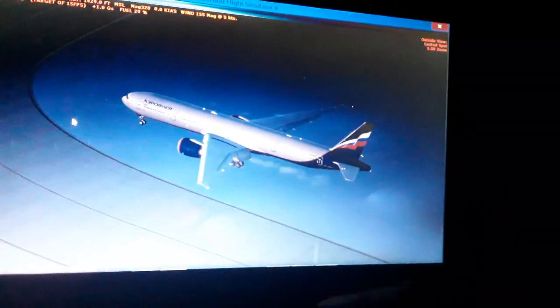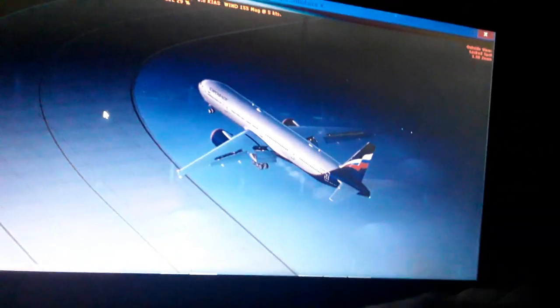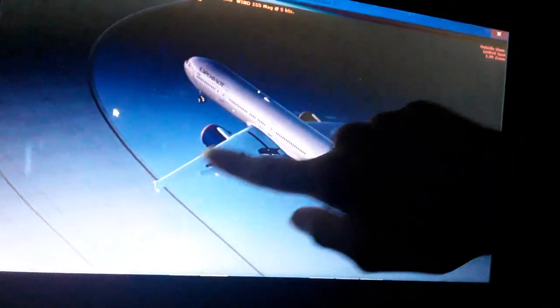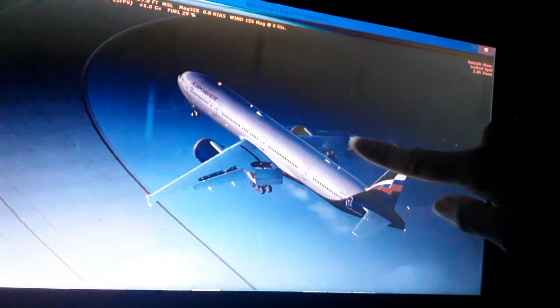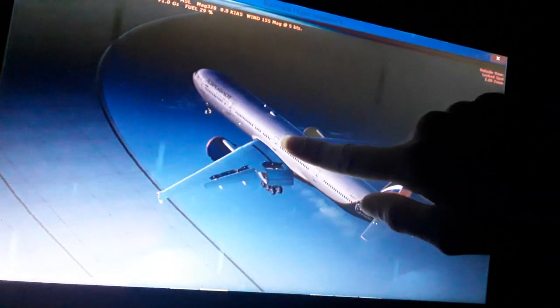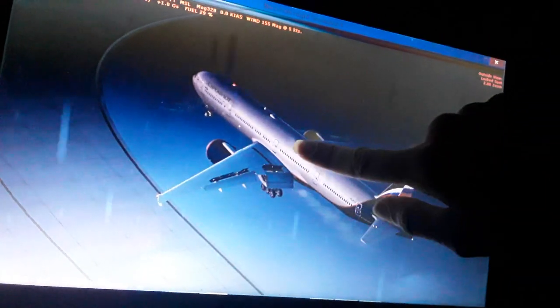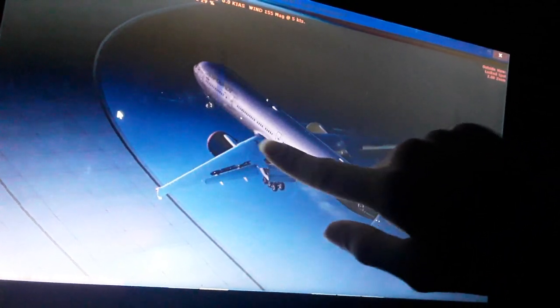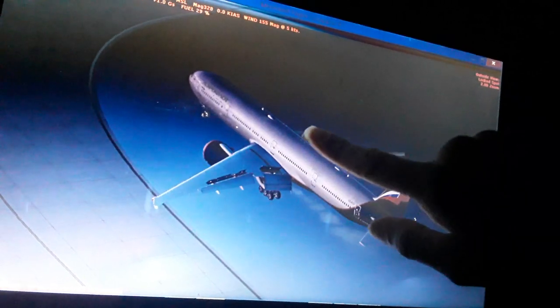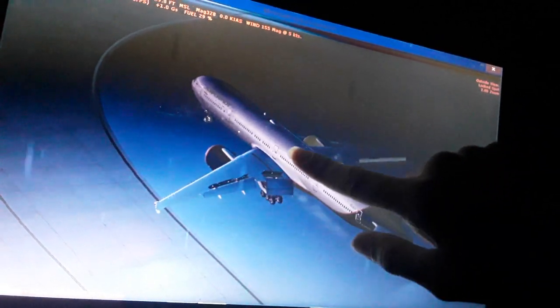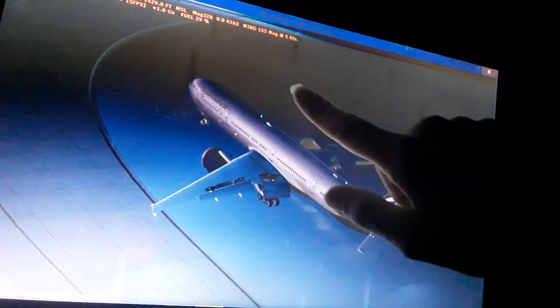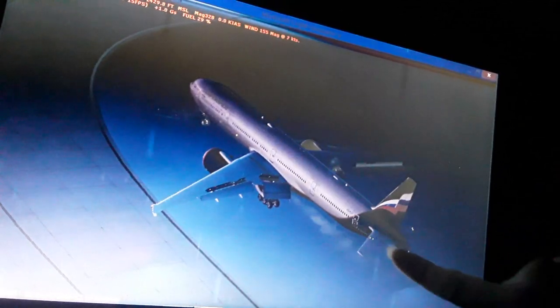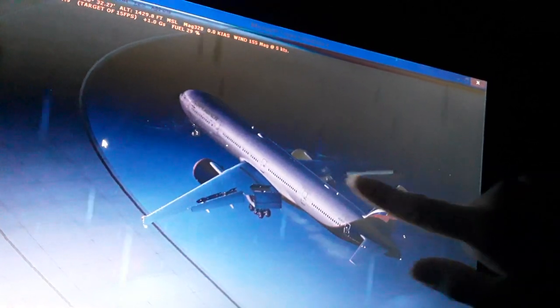So you can see here we have the aircraft. You can see the aircraft wings hold the weight of the aircraft as the aircraft flies. You have also the mean aerodynamic chord position, about 25% of the MAC. It's the position where the maximum aerodynamic lift occurs, also where the center of pressure above the wings occurs, and the stall, where the airflow becomes detached from the top of the wings, so the aircraft wings stall. About here we have also the center of gravity of the aircraft that traverses here the longitudinal axis and the lateral axis of the aircraft.